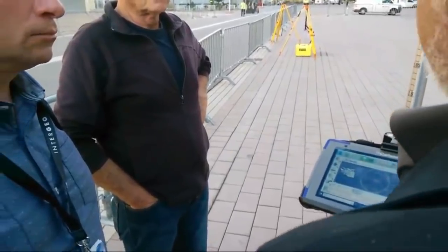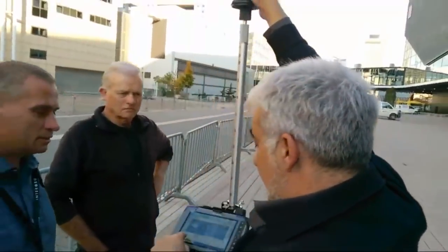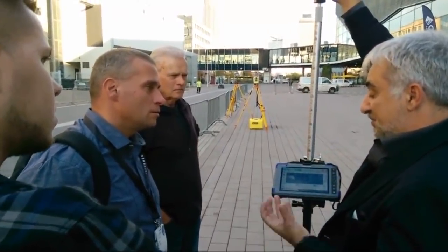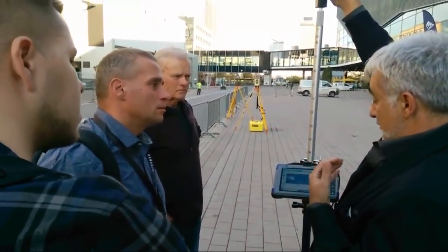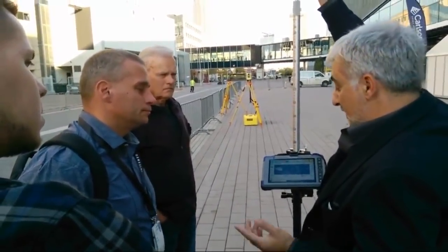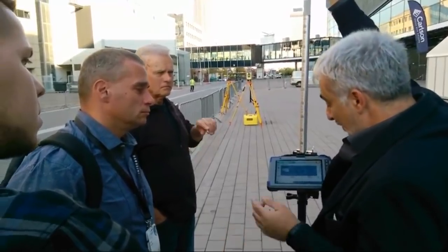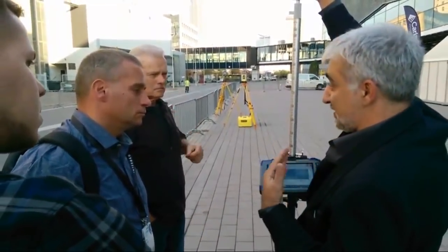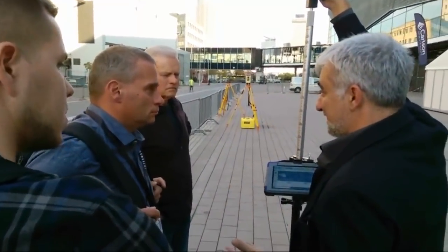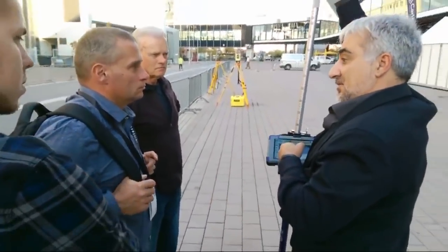So what happens if I move now? Well, you see, if I move, I have position, because all the text is turning red. The timer is turning red to tell me that backup tracking is active now. Backup tracking means you don't have total station position, but GPS takes care. Because your main instrument is the total station, you are not allowed to measure. But what is the problem to show you on the screen, or to take you to the point with the GPS? You don't need precision for that, right? So you can use GPS until the time you lock the prism again. When to lock the prism? When you need it, when you get to the point.